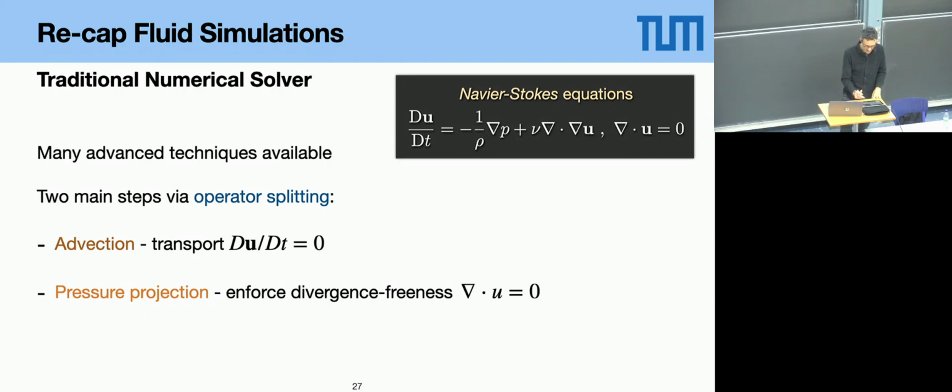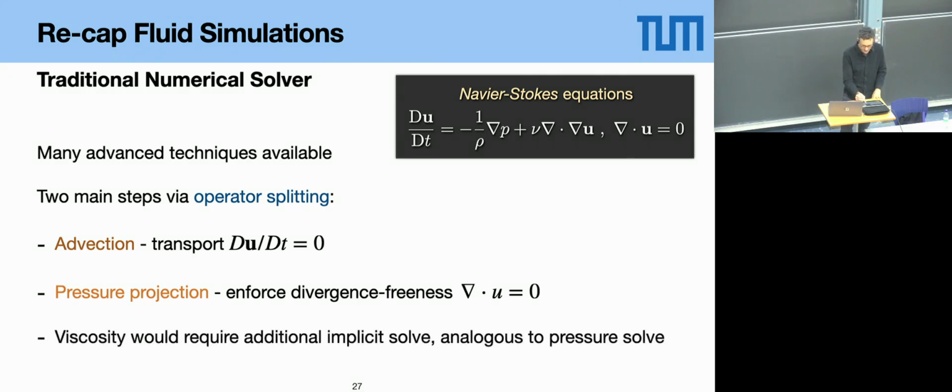And then the viscosity term, which is this one up here. This is basically a diffusion term, so I'm blurring things like the velocity out a bit. This is what we'll neglect, because in practice, especially if you have not super accurate solvers, they actually introduce diffusion. It's like viscosity. So with a simple method, we have plenty of that, or more than we want, and we don't need to spend additional effort to compute this term.